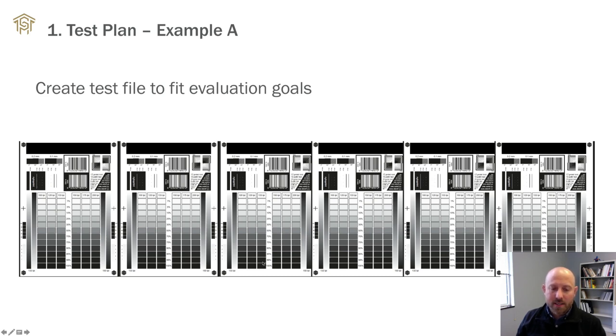halftone. We've got tone scales here. This one in particular has different LPIs. This would also give us an insight on what the best LPI to use on a particular Anilox setup would be. And then we have some stuff in here that also would help us evaluate how clean it's printing, how well it's holding the detail.